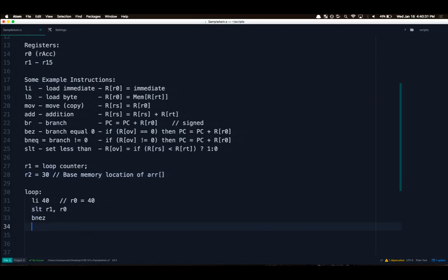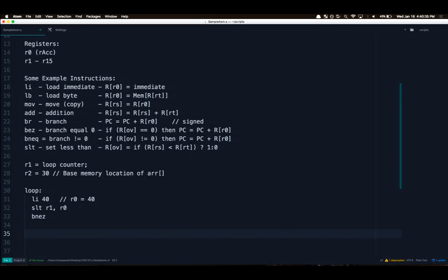Yeah. What happens to your overflow register? After you do this arithmetic and algorithm, you do need to use the overflow bit, but you happen to have to use set less than it. Yeah, so it's going to kick the existing value that's in there out, and that instruction that does write to an overflow is going to update it. So not all instructions need to write to the overflow register, just ones that you decide. So we have to include that. Yeah, in the write-up. Exactly. Yep. So, yeah, another question?